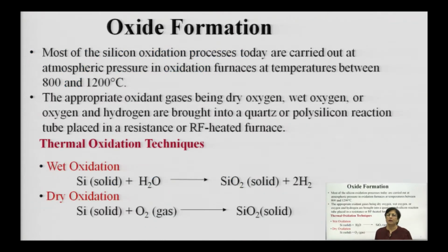technique. Now, you know already that in the silicon dioxide process, we have seen that 0.44 D of silicon is consumed whenever 1 unit or 1 D of silicon dioxide is formed. So it first penetrates into the silicon and then grows. So you have very good adhesivity, very good surface adhesion. Contamination is minimum because the contaminant species remain outside, since the growth is happening inside the silicon surface.